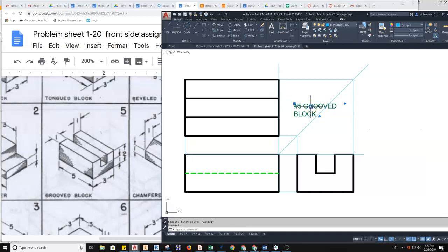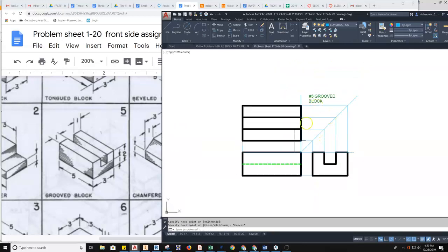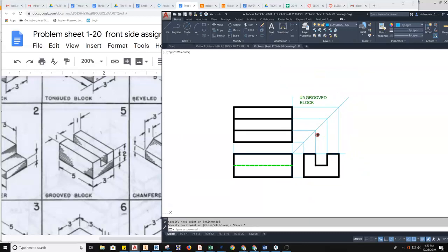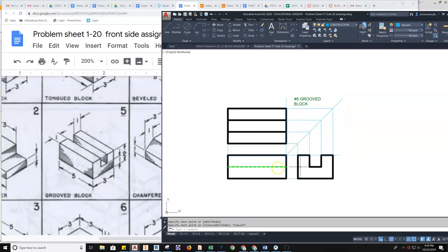The middle object, we'll just move my text out of the way here. This middle notch area, I will do the same thing over and down, and you can see that that sets up a relationship between the views as well. Comes over and down. By doing this, you can better predict where objects will be located in the multi-view drawing arena.